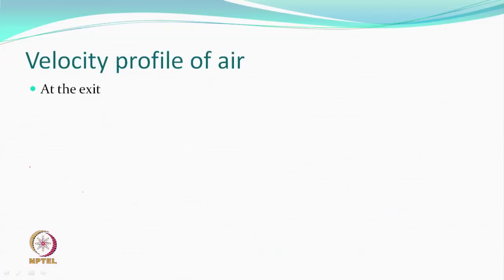Why entanglement? This is just good enough to open the filaments and move them faster. If entanglement has to take place, the speed of different filaments at any given point of time must not be the same. If they are the same, then opening will take place together, of course, and loop formation will also take place together. Entanglement will not take place.